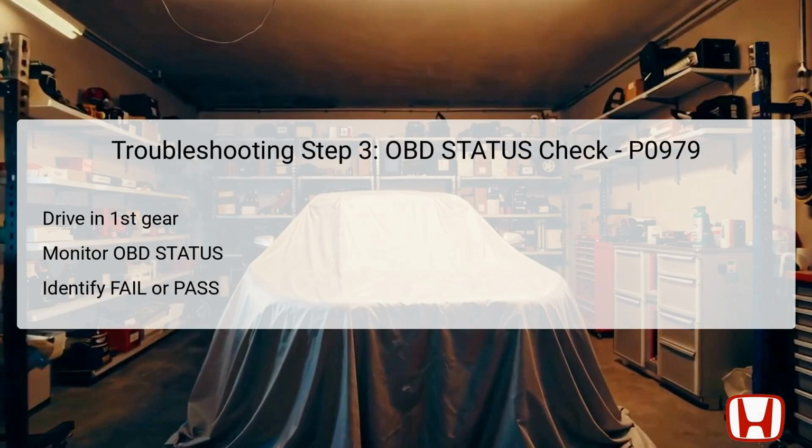The third step involves an OBD status check to further confirm the issue with the vehicle's transmission. To begin, test drive the vehicle in first gear with the shift lever positioned in drive mode for at least 1 second. This allows the system to assess the performance of shift solenoid valve C under real driving conditions. Utilize the HDS to monitor the onboard diagnostics OBD status within the DTCs menu. If the HDS indicates a status of failed for P0979, this validates that the failure has been duplicated and you must proceed to step 4.